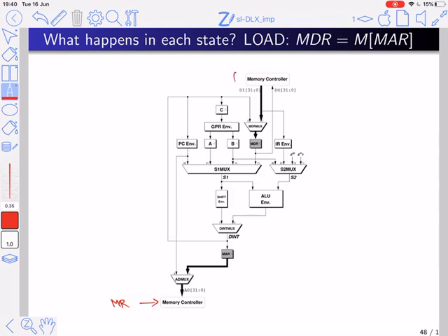So this would be M in the address given by the MAR. And it directs it through the MDR mux into the MDR. And it tells the MDR to sample this thing. So we will get an MDR clock enable signal, so that we store inside the MDR what we need to store because we wanted to perform a load. Okay. This does not complete yet the execution of the load instruction.